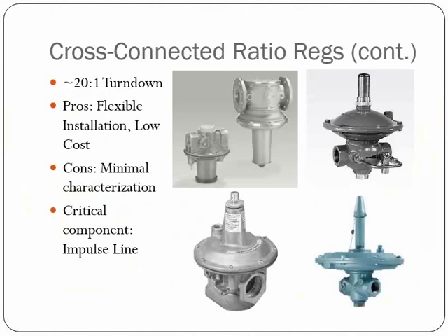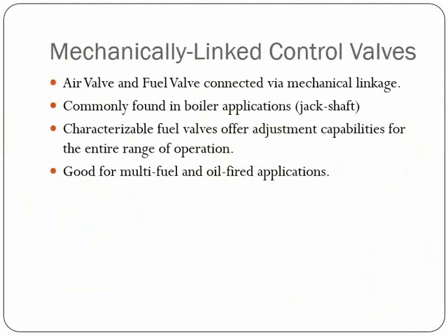The next method that I'll talk about is the mechanically linked control valves. I'm sure we've all seen these where we have an air valve and a fuel valve that are connected via mechanical linkage. A lot of times we'll see these in boiler applications as a jack shaft. They also will a lot of times have characterizable fuel valves that will offer adjustment capabilities over the entire range